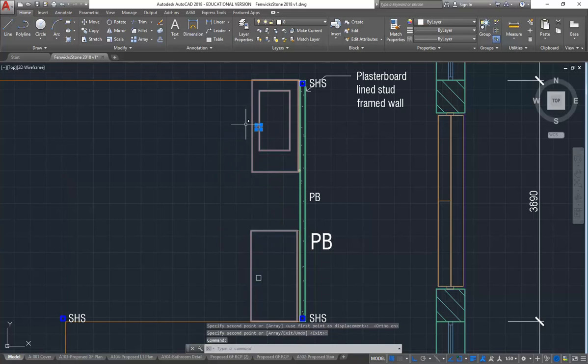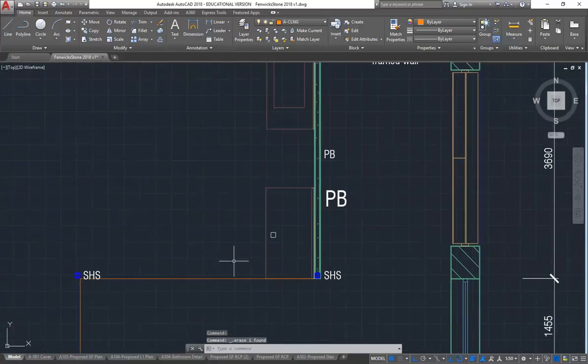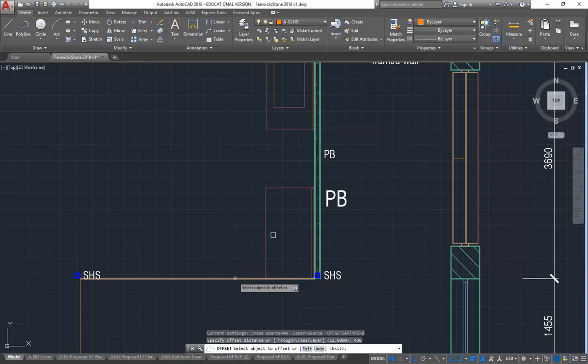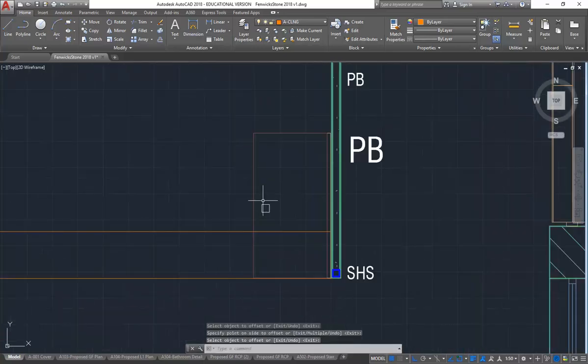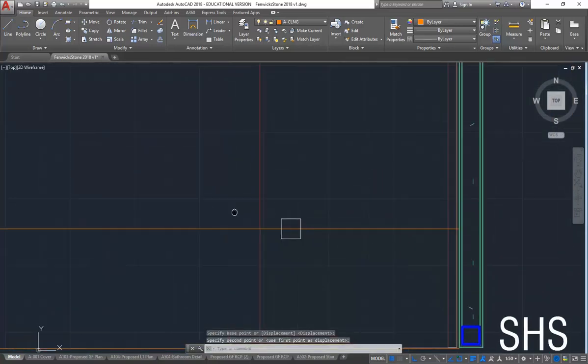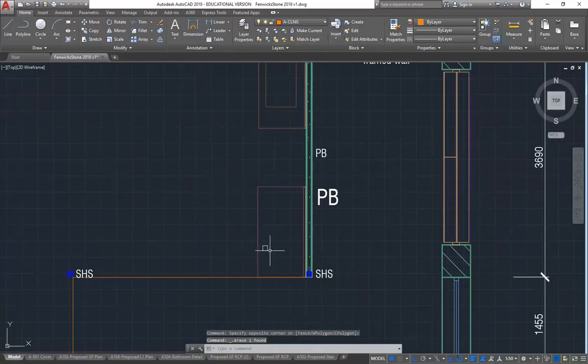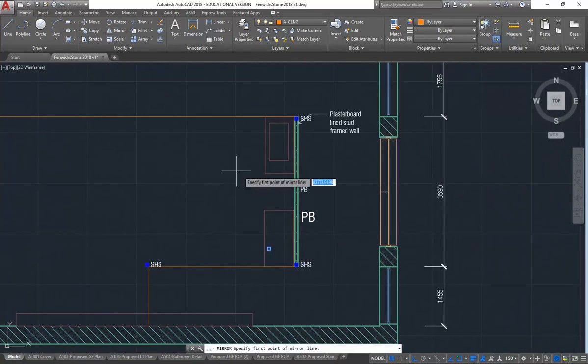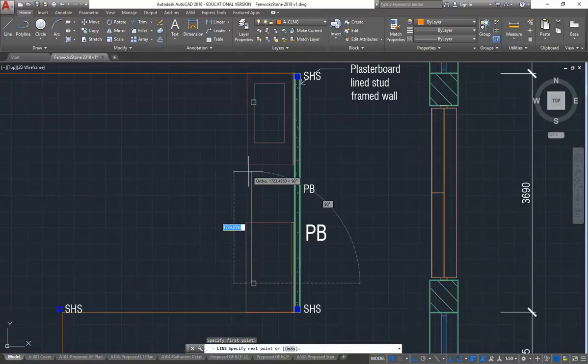So actually maybe there, if you want to place it using measurements, you can set out other lines. So here I might use offset and make it, let's say, 450. And then we can snap that light. And then use mirror and other tools like that to place the lights, but again, that's going to depend on your design.